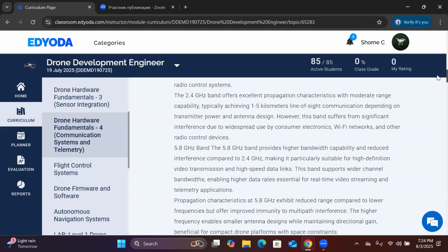Now I want to increase my range 10 times. So I want to increase my range from 5 kilometer to 50 kilometer and my endurance from 45 minutes to say 2-3 hours. How to do that? So in the RF transmitter chain, when we design the RF transmitter circuitry, after the wireless LAN module, we have to connect an RF power amplifier.